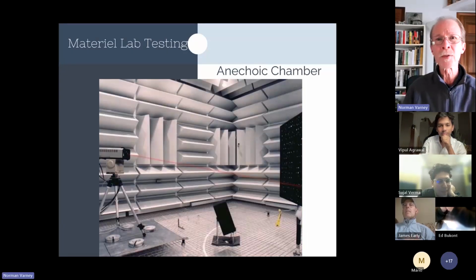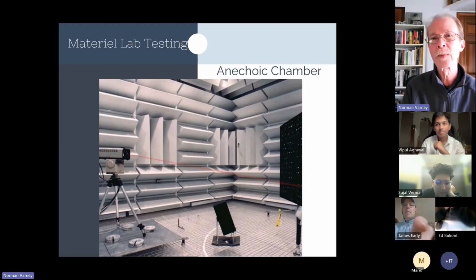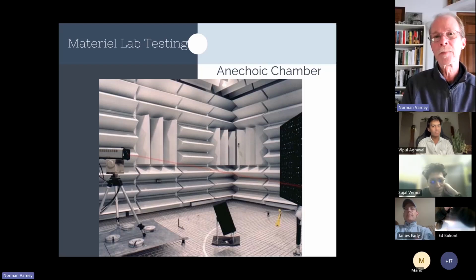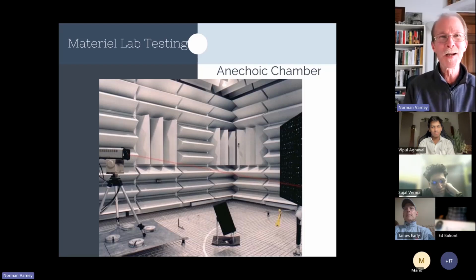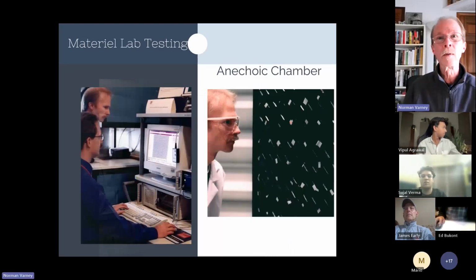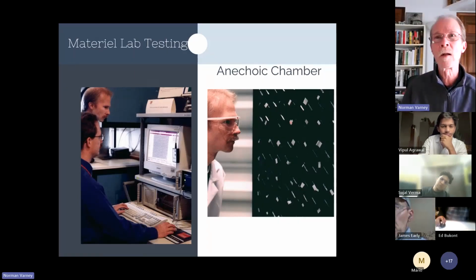Let's see, another shot. So another test on this diffuser. It was resonating, and so I was trying to find a material that we could back it with to damp the material. And this was big time back then. It still is. Laser vibrometers are still a big deal. They're expensive. But back then, this was one of the few places that had a laser vibrometer. And look, I'm actually checking and making sure it's hitting all the points.